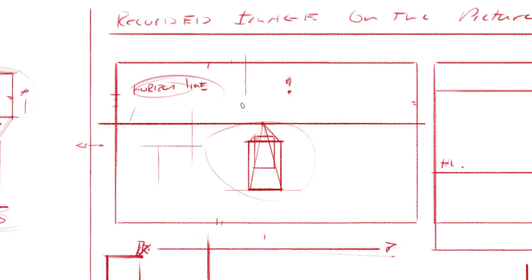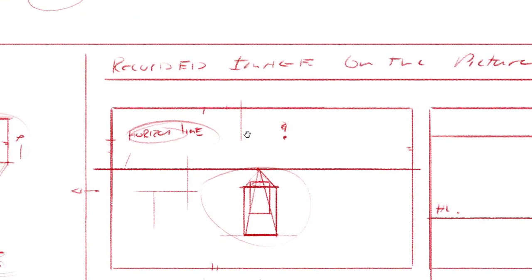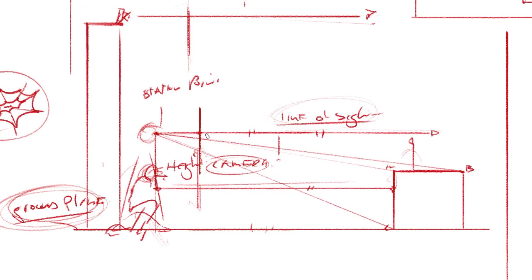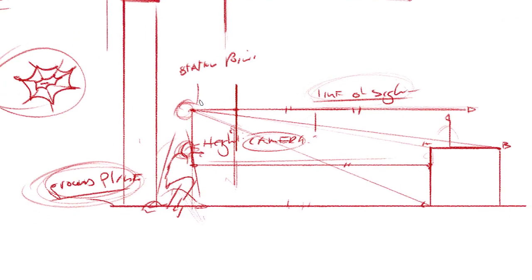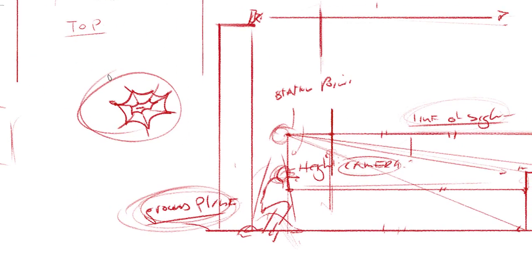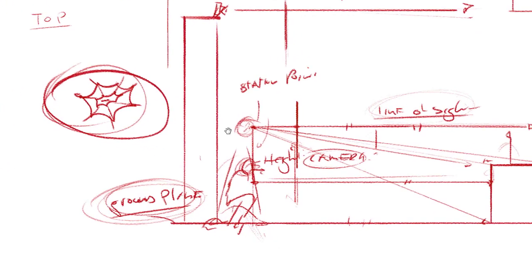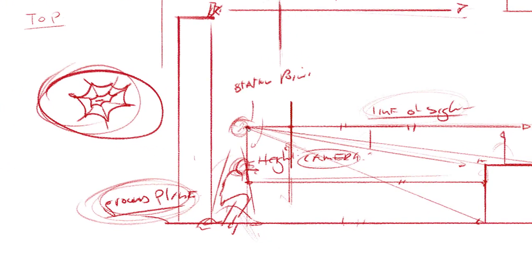So the same goes for 1-point perspective. Okay, and the reason for this is that we keep this camera looking straight ahead. So now we can tilt this head. So this guy looks towards this thing, okay? But think of the web again. If you tilt this camera, things start to happen. So the station point keeps the same height, nothing changes there. Only the line of sight tilts.